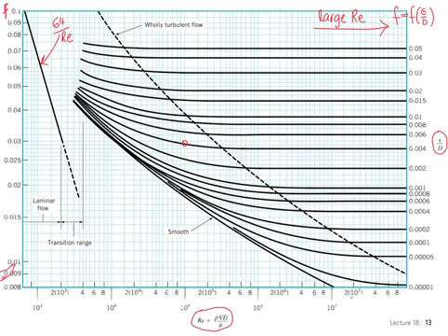F is non-dimensional, L over D is non-dimensional, and delta P over gamma has units of length, right? And rho. So can you work that out? We're multiplying by velocity, length divided by time squared, and in the bottom we have acceleration. Rho shouldn't be there. It cancels out. Okay. Typo.